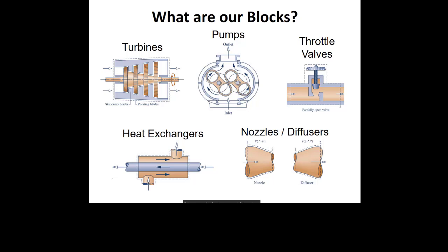And what happens when you do that is you shrink the area where the fluid is coming out, and because of that, the fluid comes out faster, right? So you're adding kinetic energy to the flow. A diffuser is kind of the opposite of that, where the area expands, and provided you're subsonic, then what happens is you're reducing the kinetic energy that's involved, or the velocity of the fluid, because it's taking up more area.